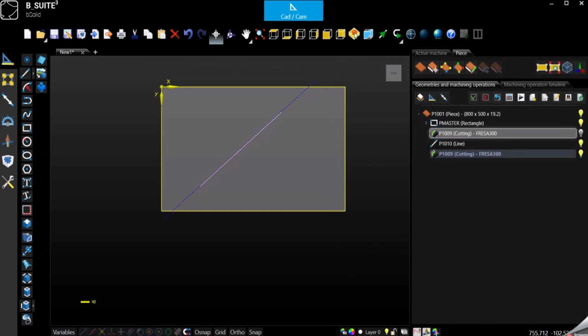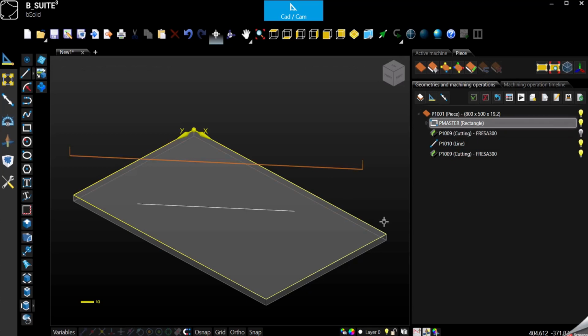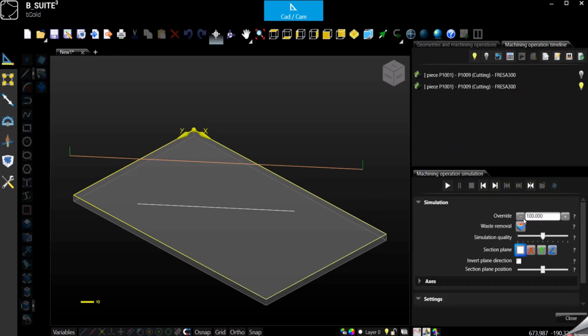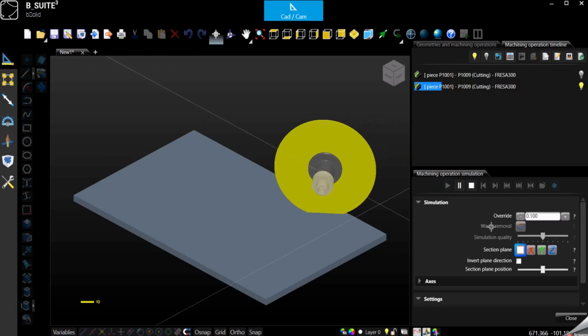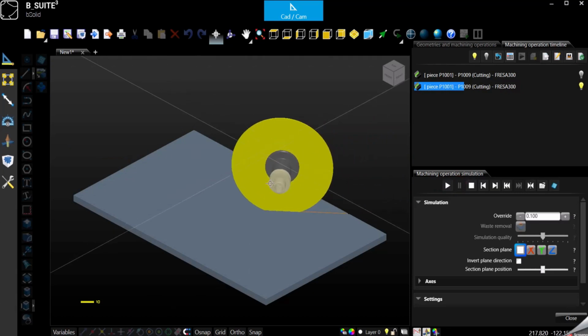And in this case, what is going to happen? Let's say that I'm cutting a panel with melamine, top and bottom. Play the simulation. Let's slow it down. Remember, my blade is counterclockwise, so it's climbing on top of the panel.